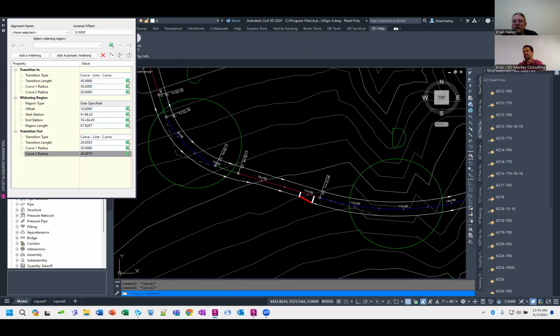If you're transitioning from one part of the road that's got rollover curb and gutter to another part of the road that's got vertical curb and gutter, and the cross pan is different, and you're using that edge of asphalt as the target for your lane, then your widths are going to change, and you can use offset alignments for things like that. They've got a lot of potential.